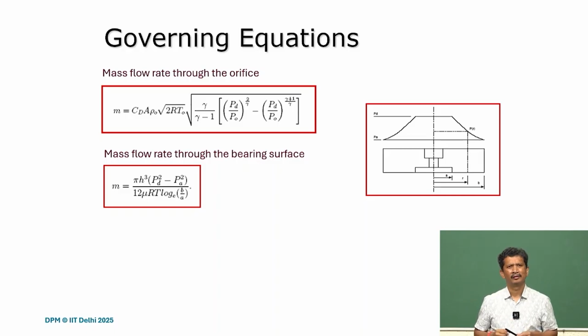So there will be no contact bearings, no friction, zero friction, so maintenance free, no backlash associated with the friction and the stiffness. Since there is no friction, there is no hysteresis, and therefore it's easy to achieve higher precision and repeatability.